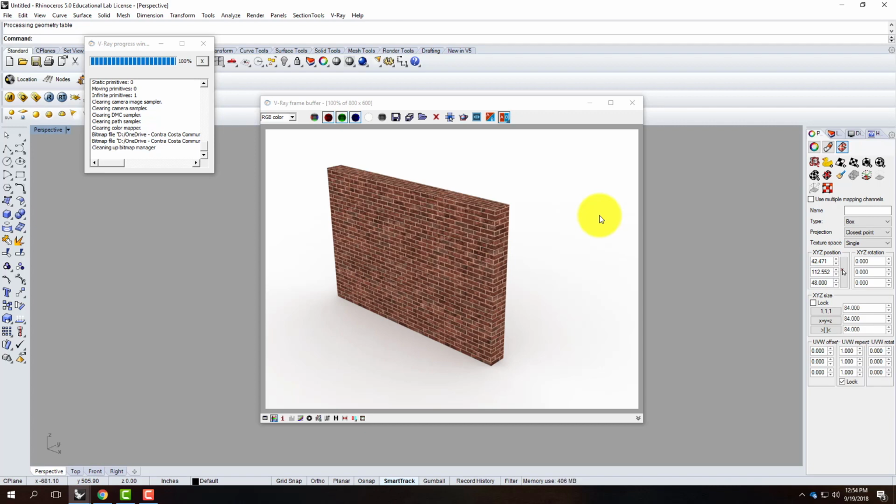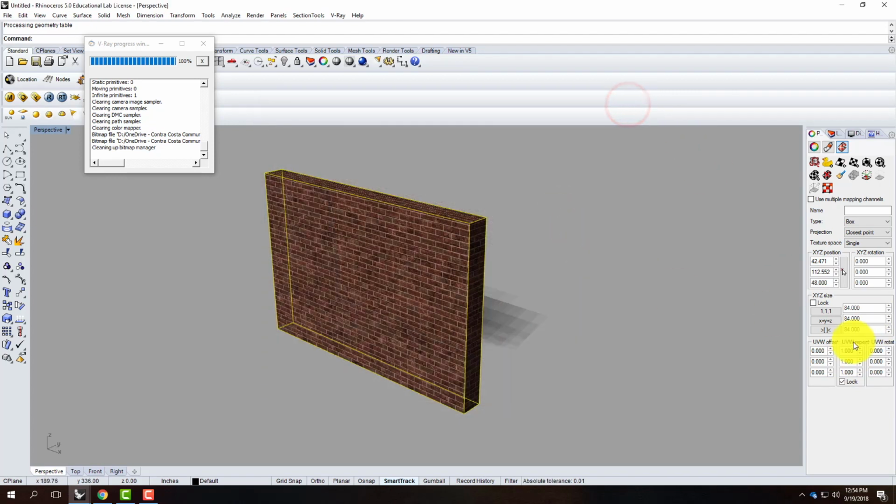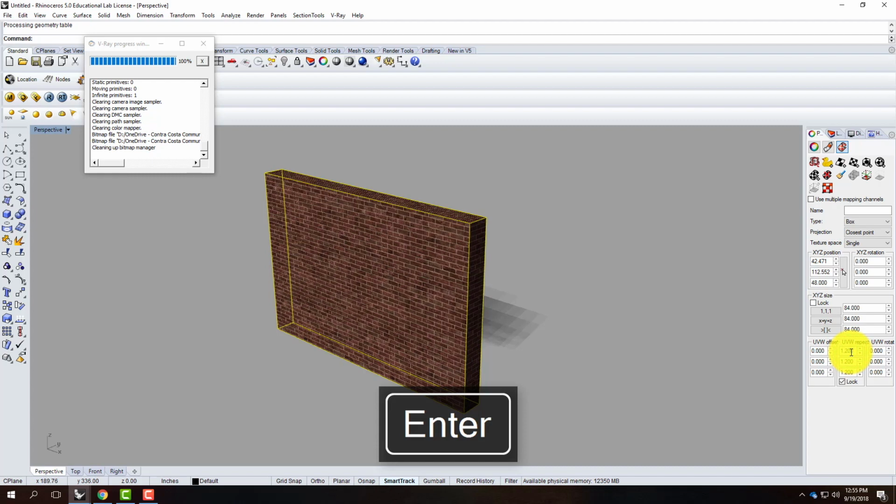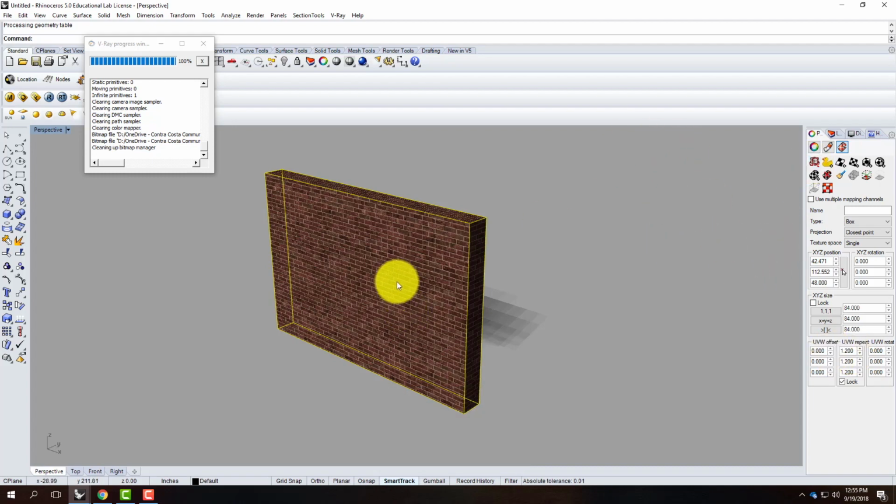And for most of this, it's a matter of getting it to x equals y equals z for average, and then adjusting this UV repeat. So if this didn't quite look right, we needed a couple more bricks, go up by 1. So 1.1, just a little bit more dense. 1.2, just a little bit more dense. It doesn't take much to adjust just a bit. And so that can get us to where we have that nice looking brick wall.